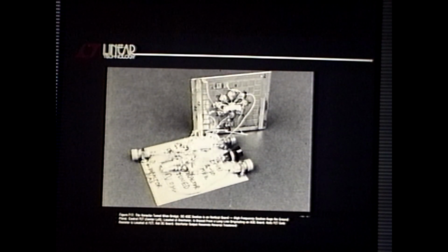Here is the varactor tuned Wien bridge version of this thing. This thing here, I elected to build on 2 breadboards. This is the AGC. You notice there's not even a ground plane here. And the reason is the AGC is slow. It's basically DC to 10 or 20 hertz AGC kind of action. I didn't waste time with a ground plane.